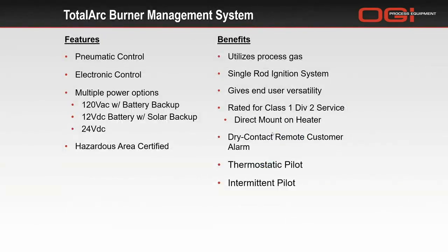Some of the options and features we have is, as we discussed, pneumatic versus electronic control. Power options are the same as we have on the TotalArc Relighter: 120 volts, solar with battery backup, and 24 volts DC. It is also listed to operate in a hazardous area location under Class 1 DIV2, and you are able to install it on the heater. You do not have to move it away from the heater to get that classification.